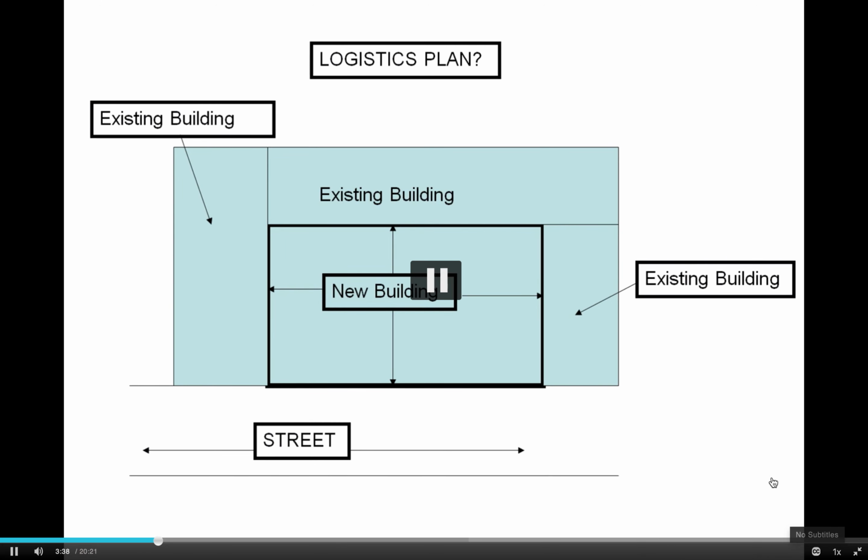Right, the first step when you're planning your project, when you're bidding a project, is to understand your surroundings and figure out how to get things in and out of that project, how to demo whatever might have been there in the beginning, how to bring excavated material out, how to feed materials and personnel into the site to work on it, and then as you start coming out of the ground, how do you feed those new flights as you go further up the stories in your building.